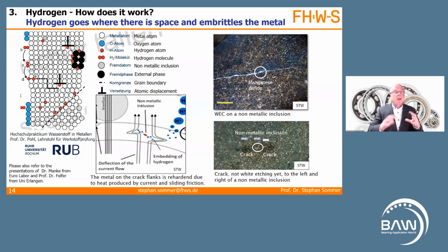Now, more and more hydrogen can accumulate in the crack. The devil's circle has begun. More and more embrittlement by hydrogen, more and more notch stress, and more cracking.